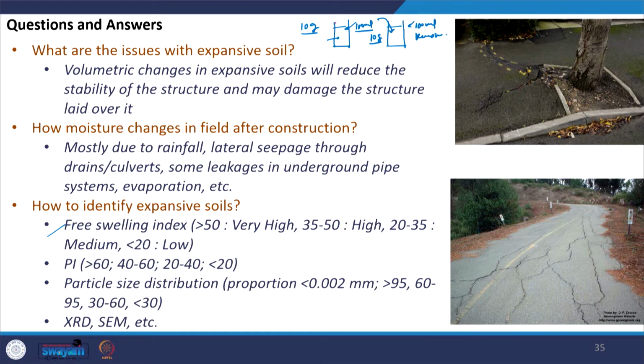We understand that presence of moisture will lead to the formation of the diffuse double layer, because of which if it is an expansive soil there will be an increment in the volume. Okay. But kerosene is not going to react, or it is not going to participate in the activity with the clay minerals to increase its volume. In the kerosene we will not see such type of expansion.